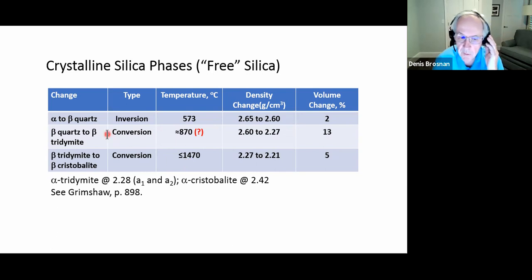And so the deal is that certain impurities tend to function as mineralizers, meaning they accelerate that conversion over to cristobalite. Some of the alkalis tend to do that. And so that's the reason in ceramics made from crude clays that we tend to get cristobalite above 1200 degrees, not up here, way up here at 1470.